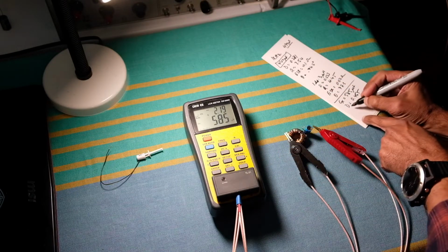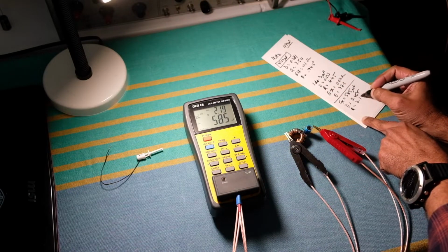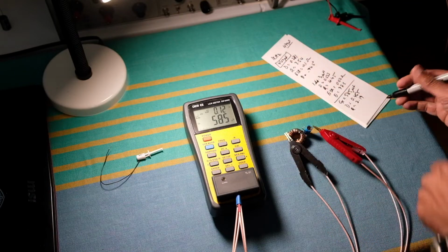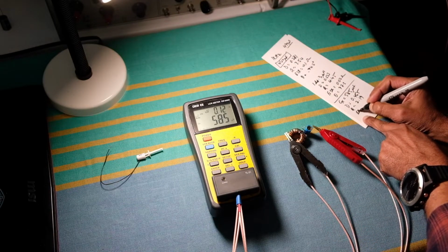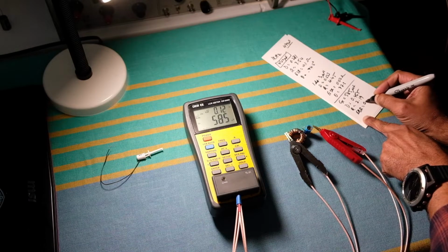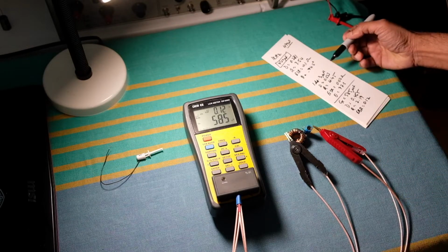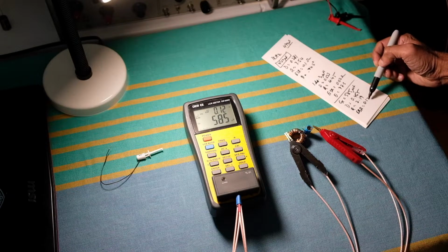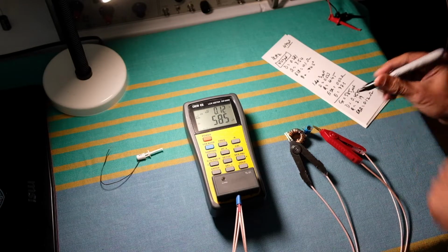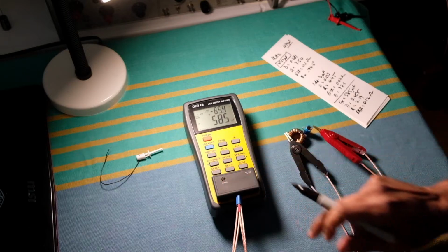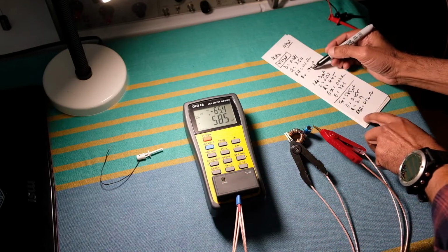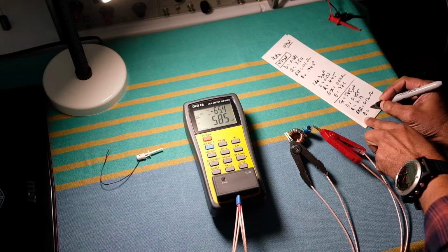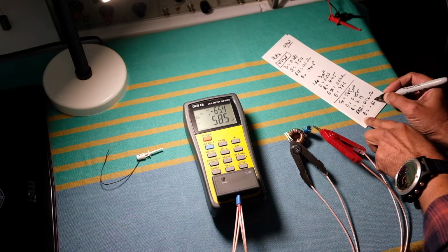The Q has now fallen to 2.19, and the ESR is 0.12, which if you recall from previously we had 0.1 ohms and 0.02, so that makes sense. And the phase angle has decreased from minus 74 to minus 65.4.